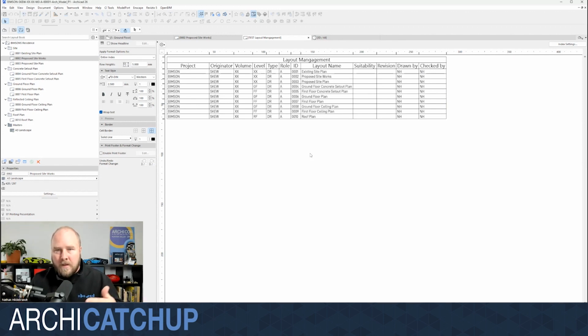So your individual clients may say deliver the project in accordance with ISO 19650, but if they then advise you as to the naming strategy of their containers and their revisioning strategy and suitability strategy, it may be different to this. So the key thing is remembering that this isn't the only way in which it's going to occur. A client's going to bring a variety of different solutions with them along the way.